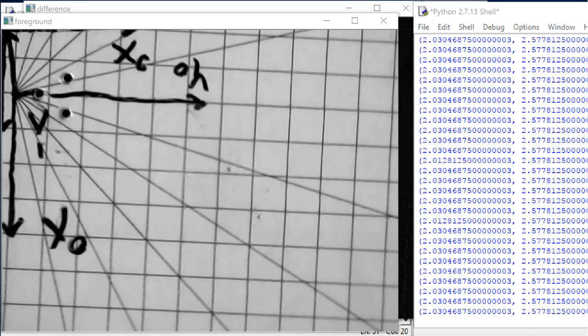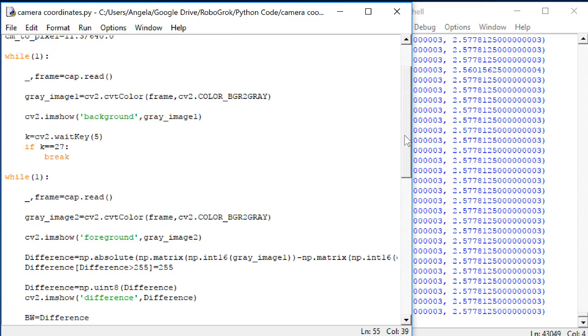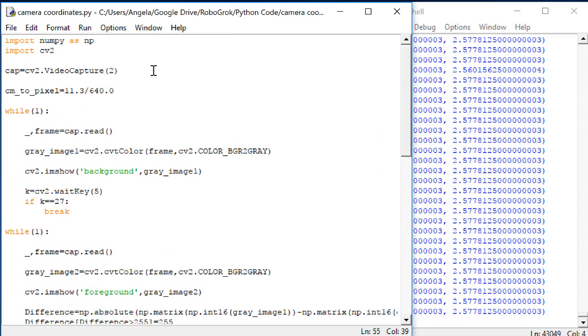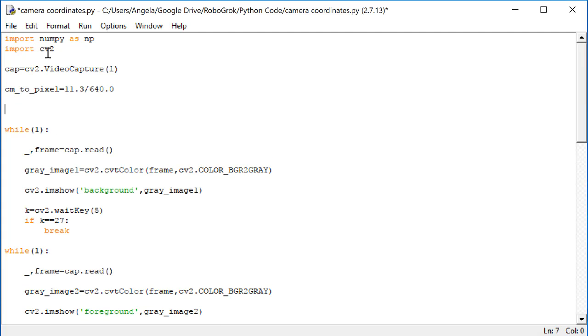So now that we have both the rotation matrix and the displacement vector, we can go back and put these into our code. Let's stop the Python code from executing by hitting escape. The homogeneous transformation matrix isn't going to change as the code runs, so let's do the calculations up here at the top. Let's first calculate the rotation matrix.